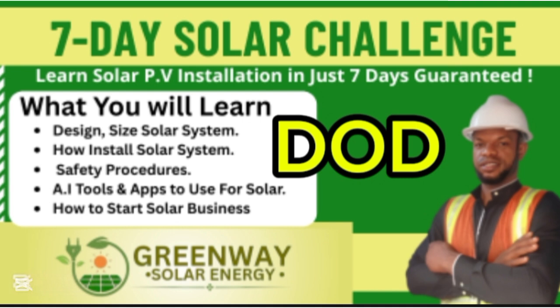Do you understand that? Tell your clients, once you begin to hear all those beeping alerts from inverters, please tell them to shut down. Some lithium batteries have their own inbuilt BMS, so that once the battery gets to its depth of discharge limit, it will give a warning, and then some of them shut down automatically.